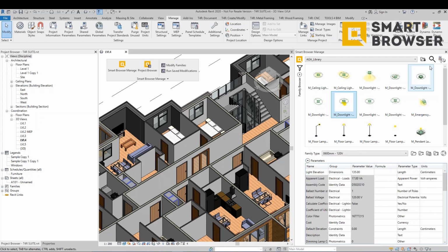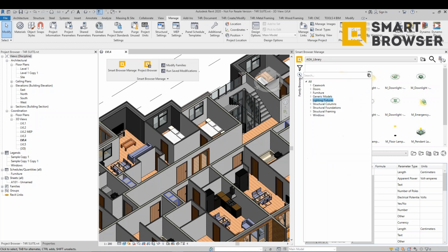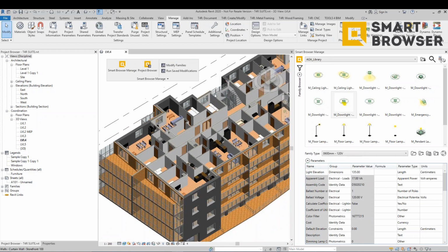So now finally I will show you the sort mark. This is actually a really powerful tool that lets you sort and number elements in a number of different ways. So you can write in your classification numbers, your codes to the elements that you use in your company, and that should be basically consistent throughout the whole project, because previously we were able to use SortMark only on elements that are actually used in the project, on element instances. But now we can number the elements that are in the external library.